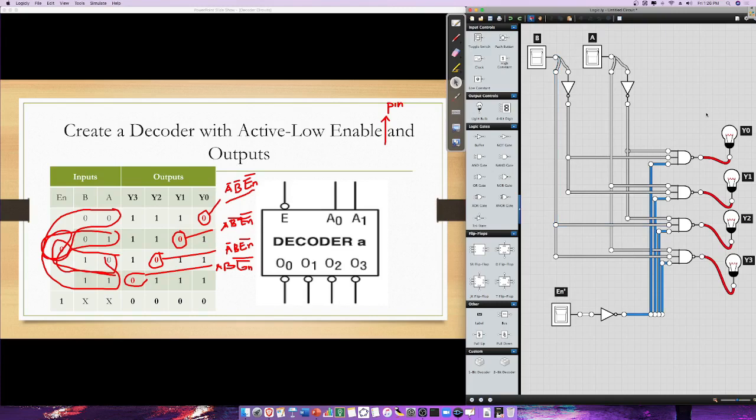Okay. Take note. Let's simulate this one. Take note, the enable pin here is logic 0. That is why you can see the output here. And since the inputs are logic 0, meaning to say it is at Y0, the output in Y0 is 0. It means it is an active low output.